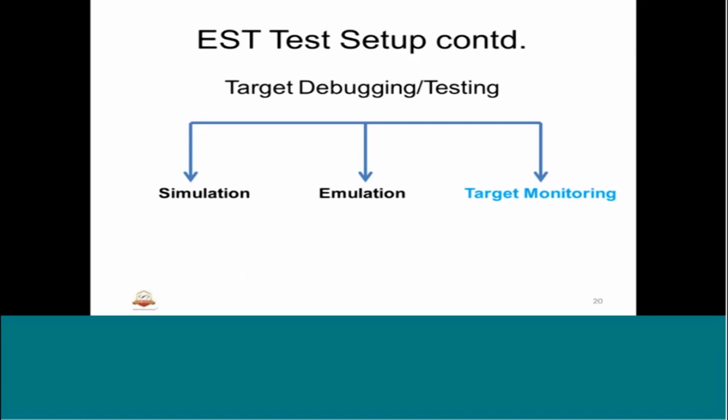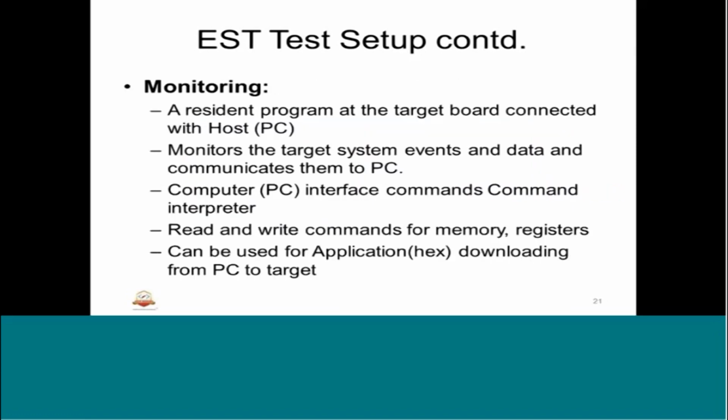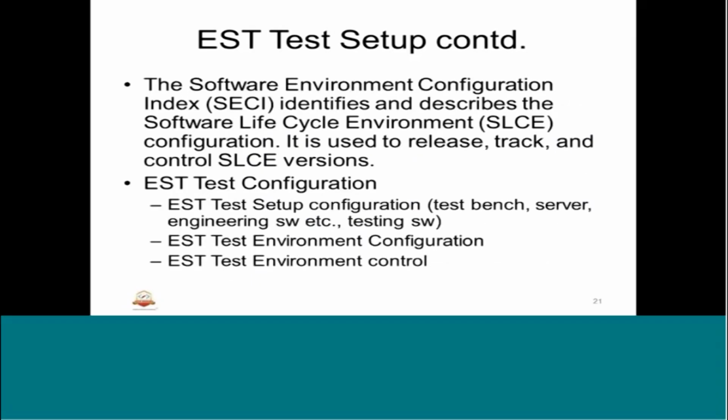The next technique is the target monitoring, where there is an already built program running on the target, which will have an interface with the host, and there are commands for read and write with the help of which the target is interacted.